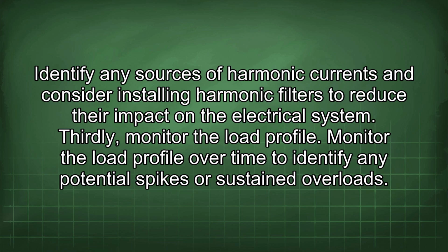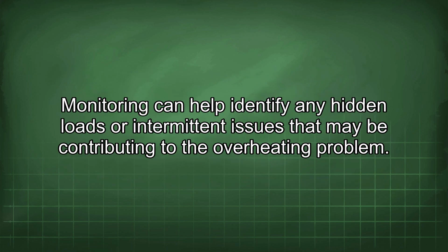Thirdly, monitor the load profile. Monitor the load profile over time to identify any potential spikes or sustained overloads. Monitoring can help identify any hidden loads or intermittent issues that may be contributing to the overheating problem.